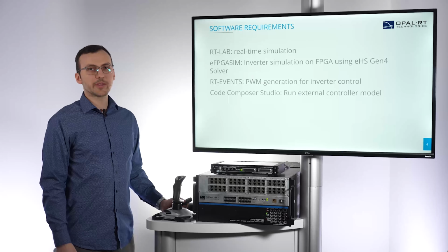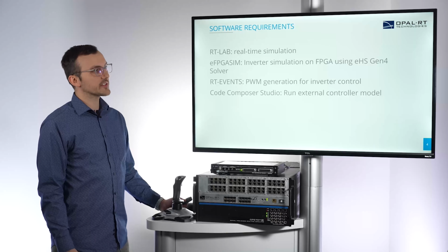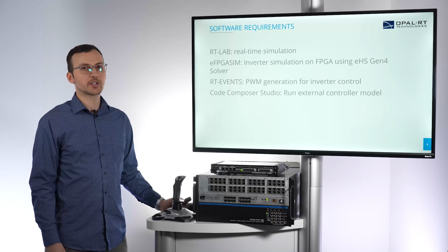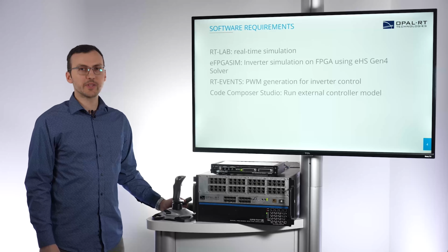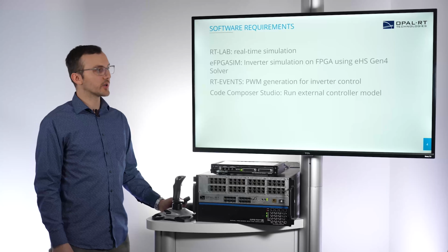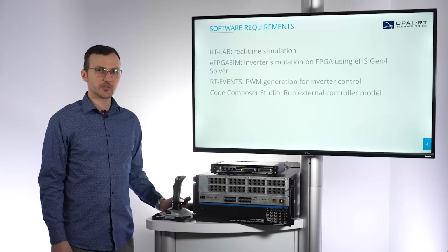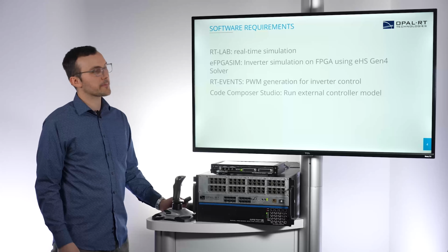RTLab runs the real-time simulation. eFPGA Sim runs the inverter simulation on the FPGA using the EHS Gen 4 solver. We have RT Events that generates the PWM signals required to run the inverter switches. And finally, we have Code Composer Studio to run the model on the OP8666.